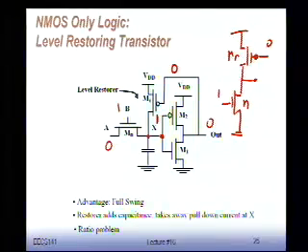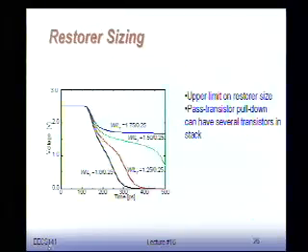So obviously the message here is very simple. The only reason we have this restoring device is to make sure that we can pull it up to VDD. So make it weak compared to the NMOS network. And if you do so, then you don't have any problem, because the weak device has small capacitance. That's nice, and it allows us to switch very nicely in both directions. So you have to be aware of that. It takes some care.